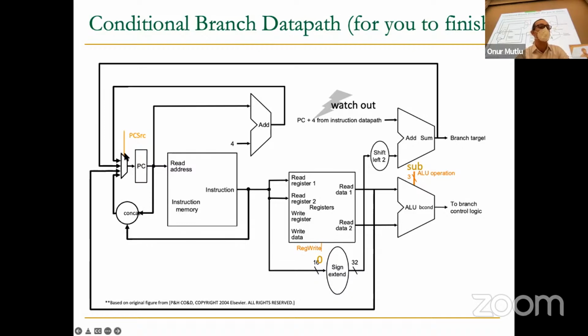So this multiplexer is controlled partially by the instruction opcode and partially by the result that's generated by the ALU, because you're dependent on the branch condition, as you can see, right? And of course, everything else is do no harm. So don't forget to do no harm. If the instruction is not modifying a destination register, don't write to it. And we're not even showing the memory over here, because this instruction has nothing to do with main memory, right? So basically, you should not read from memory or write to memory either. So this is for you to finish and think about.